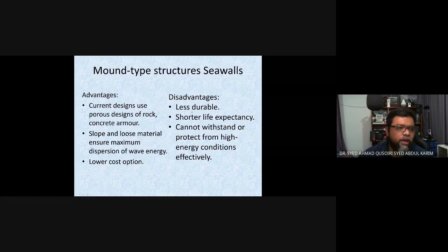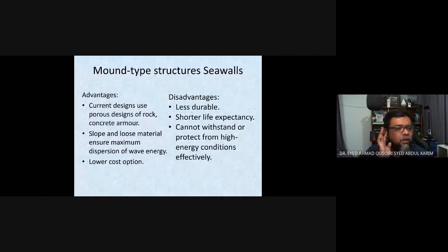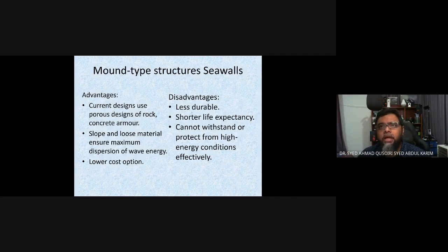Disadvantages: less durable. So that's why it can only be used in areas where the wave energy is a bit low. Shorter life expectancy, meaning that it needs to be maintained periodically. Any stones or boulders that have been taken out need to be replaced. It cannot withstand or protect from high energy conditions. It can't, because high waves will cause the stone itself to be taken out over time.